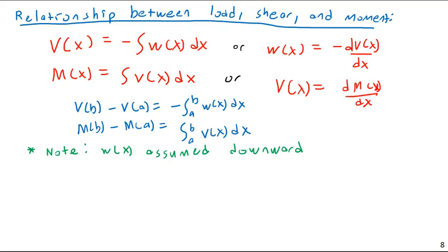It's actually fairly common to have negative moment, and if you study more beam theory, you'll learn that you can have negative moment from positive distributed load, essentially when a beam goes into double curvature. But it's very, very rare that you will have upward load on, say, a beam.